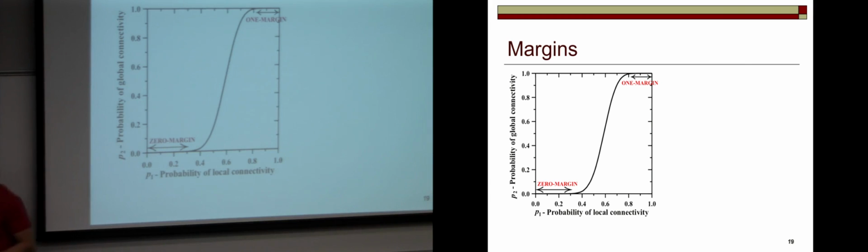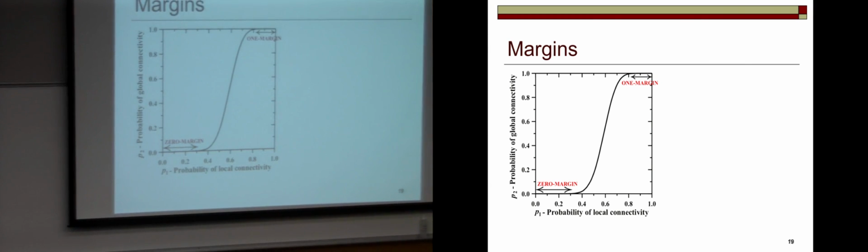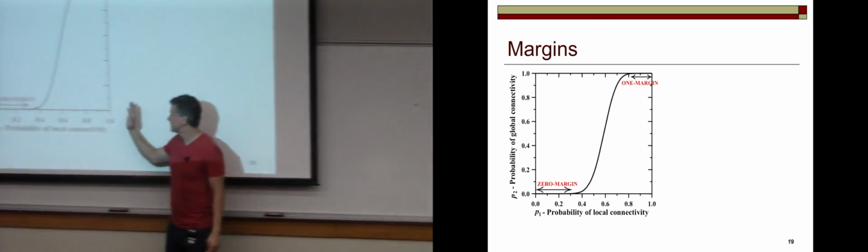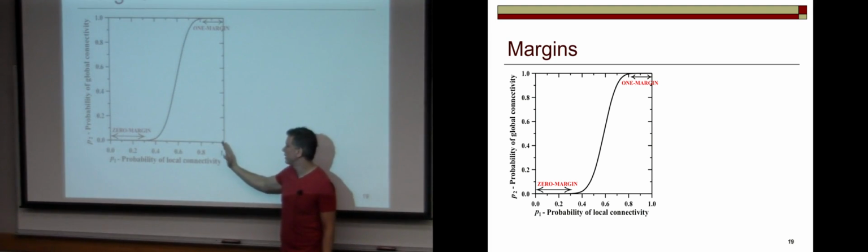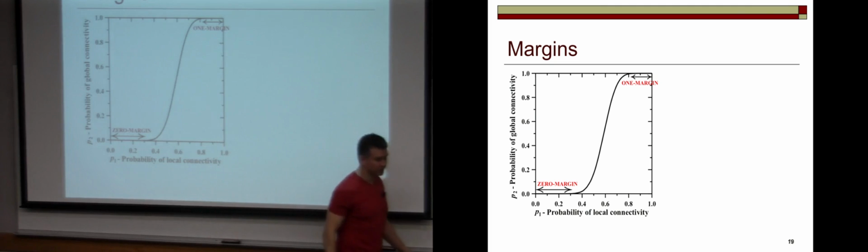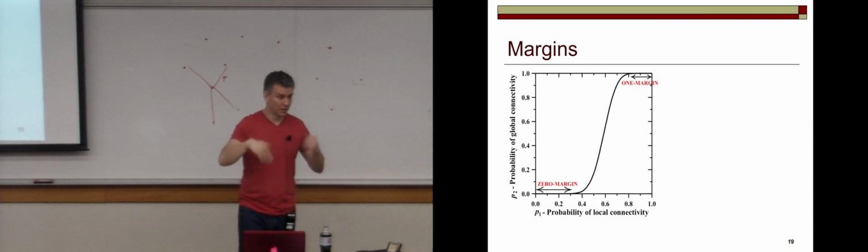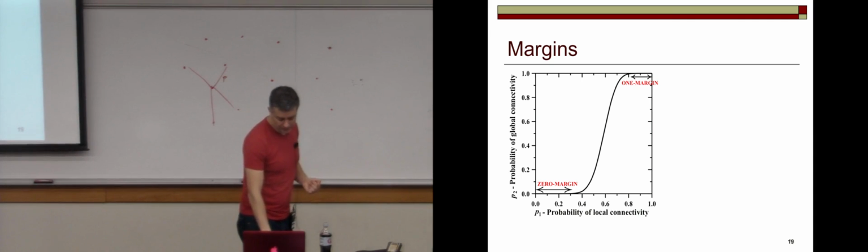And off on the other side, we have the 1 margin. The 1 margin is the area where we're supposed to have all black, but we start to have some white squares. And as a result of having some white squares, we increase the probability we don't have a connection, but for what region can we still call it reliable? The 1 versus the 0 might be defined as a probability of less than 0.01 of not getting what we expect here.